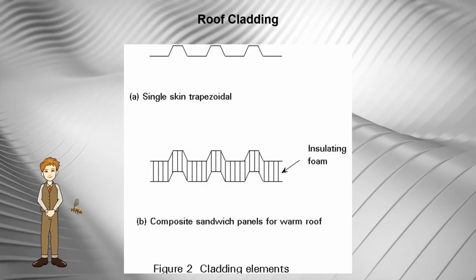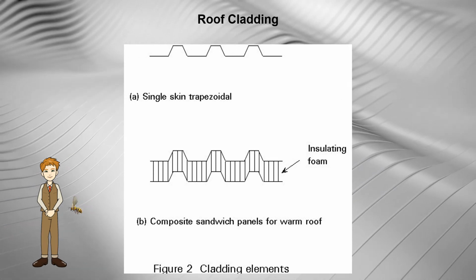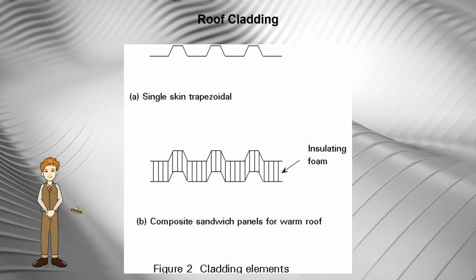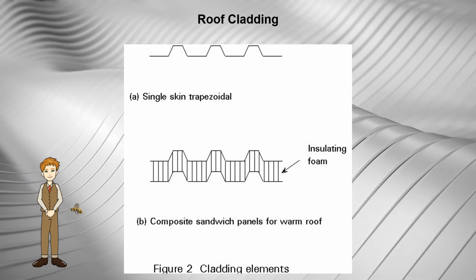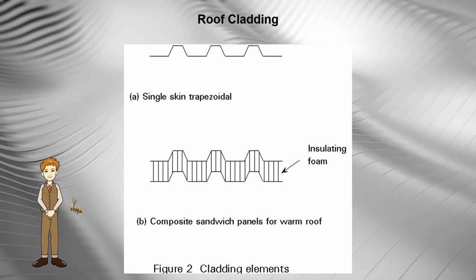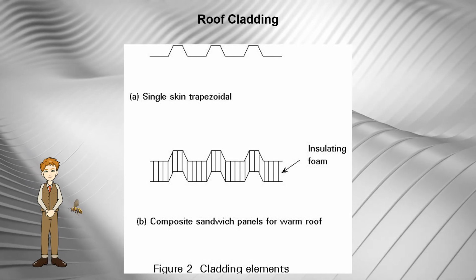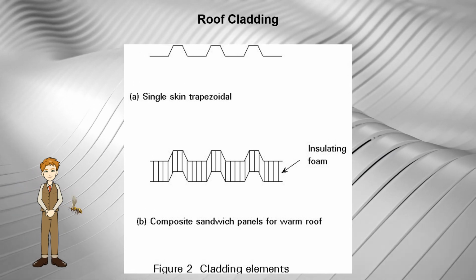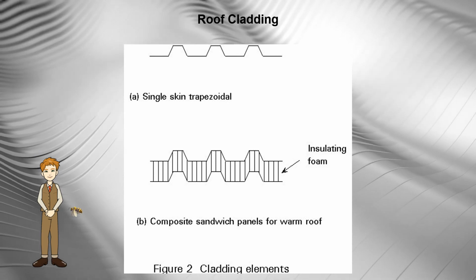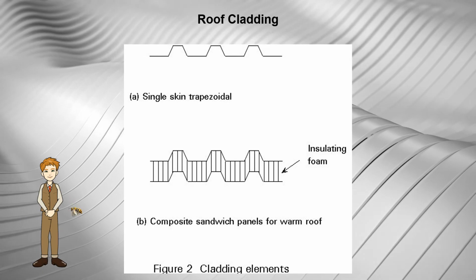Roof cladding. Single skin trapezoidal roofing. This is the most basic form of cladding construction. The main problem is to prevent condensation since it is difficult to exclude damp air from the undersides of the sheeting. The internal appearance is utilitarian since the insulation usually takes the form of unrolled thermal quilting supported on wire mesh or rigid board supported on T-bars.